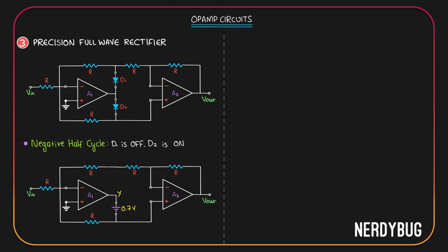Now, let us say the potential over here is V. Then the potential here will be V. That means the potential at this point is V. Since the op-amp will satisfy virtual ground condition, potential here will be V and hence potential here will also be V. For the first op-amp, non-inverting terminal is at ground. Satisfying the virtual ground condition, potential here will also be 0.